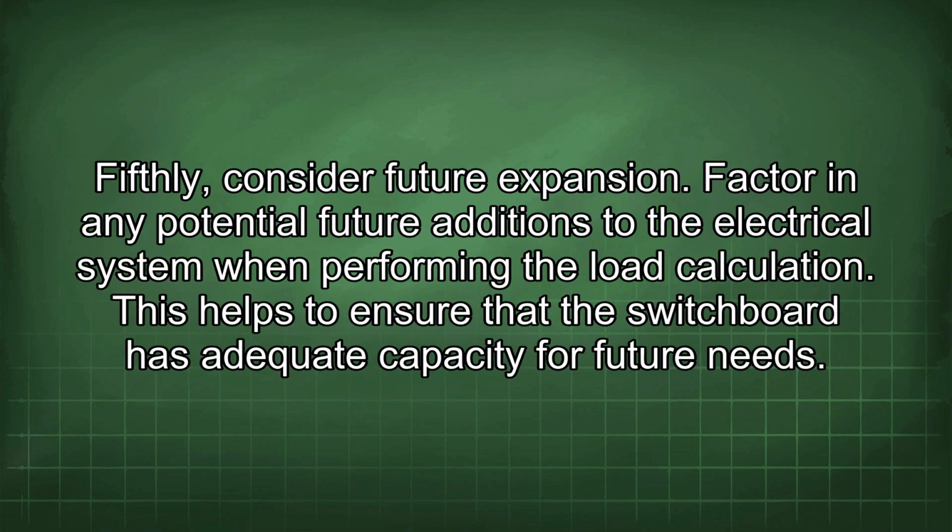Fifthly, consider future expansion. Factor in any potential future additions to the electrical system when performing the load calculation. This helps to ensure that the switchboard has adequate capacity for future needs.